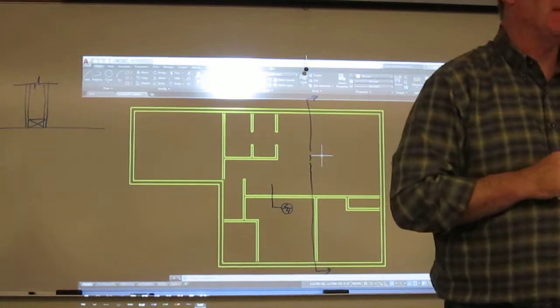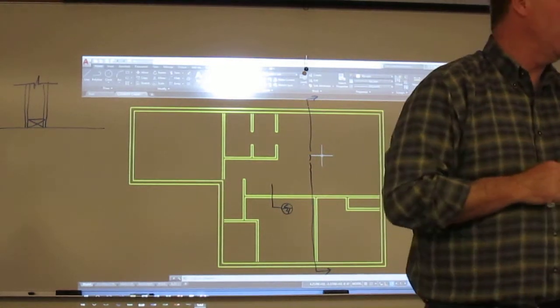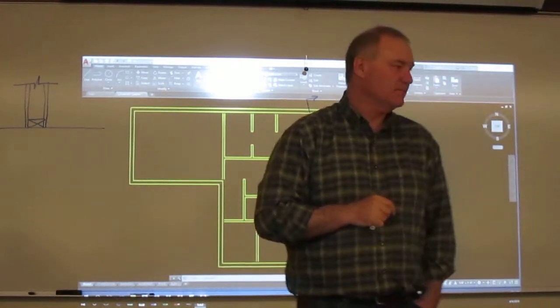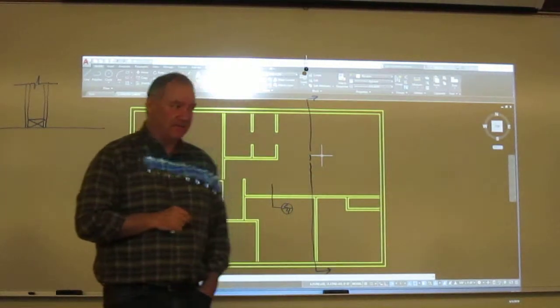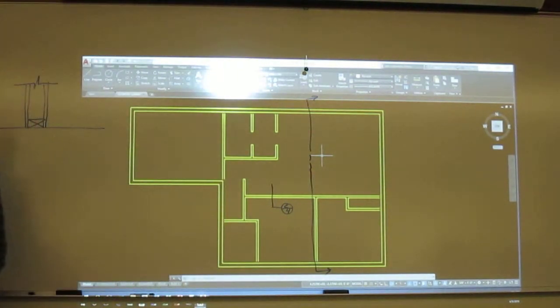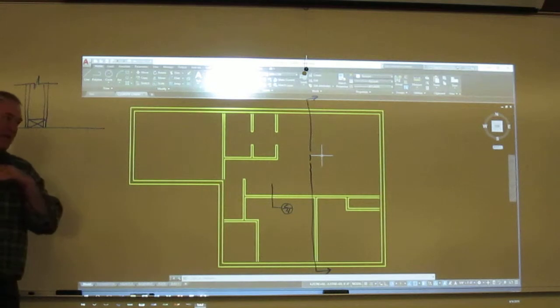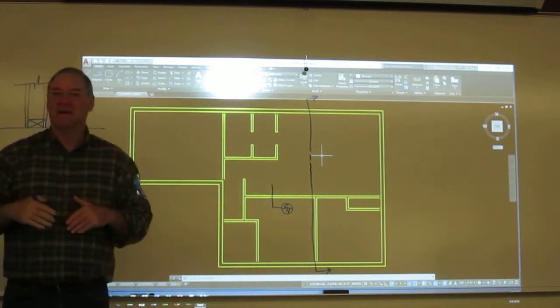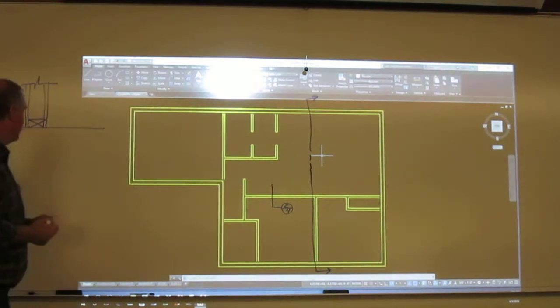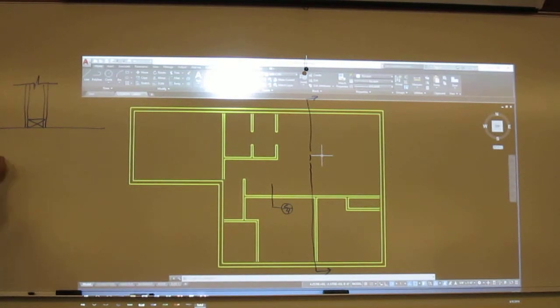We'll just stick with the IRC on this instead of calculating. 12 inches is the width. Now, generally, we can go down to 6 as the depth, but nobody's going to go to 6. Okay, so make them 8. Now, how you're going to draw that is we're not going to come in here and do a basement floor and then a 12 by 8 footing underneath it. We don't need to do this. We'll pour it at the same time the basement is being poured.